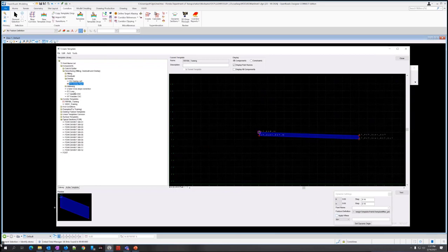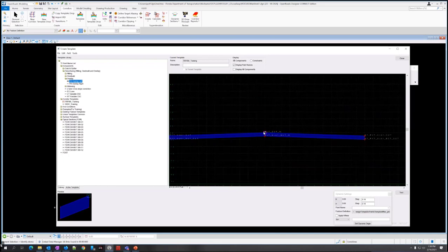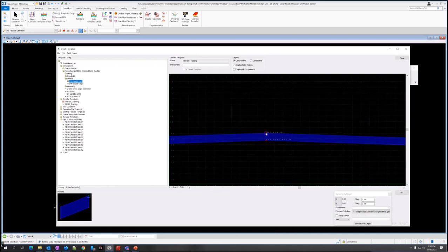Now we're going to bring in the pavement overlay left, and drop it in the same way. Make sure that the little plus for the point turns white. That means it's snapping to that other point, so it didn't create an extra point and actually just merged those together.